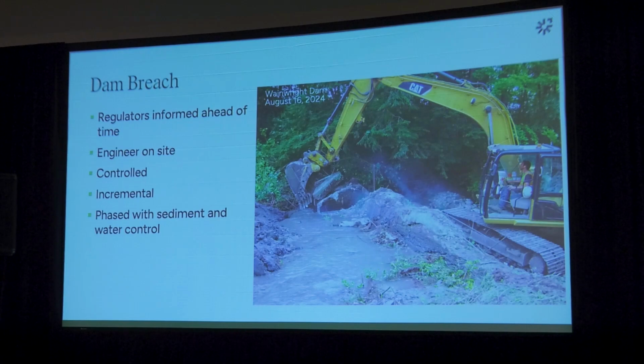I think also making sure that this is controlled, incremental, having a good plan in place, especially if it starts to crumble faster than expected, what's going to happen. We like to have the contractor have some extra stabilization materials on site during these times, or at least maybe some extra pieces of concrete that might be able to be used to bolster an area.